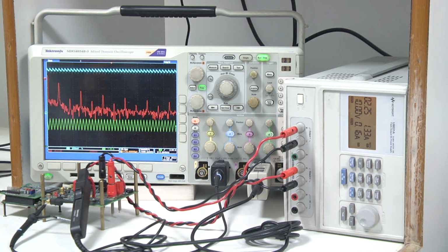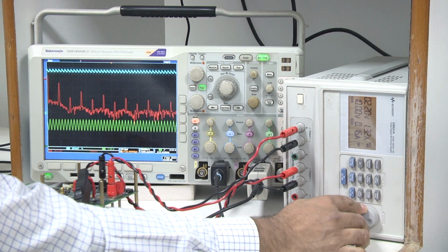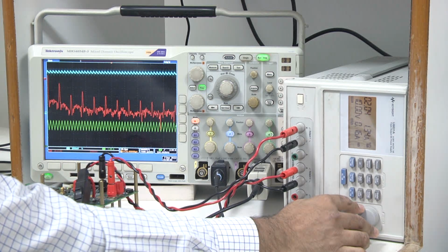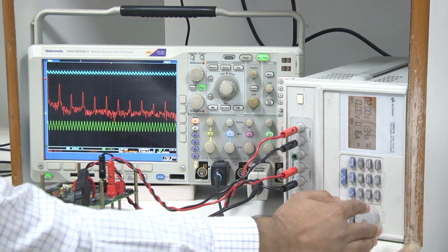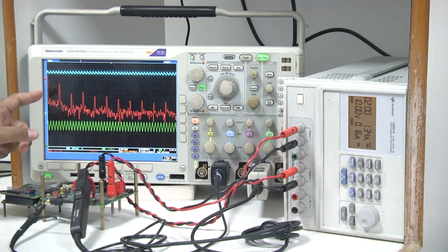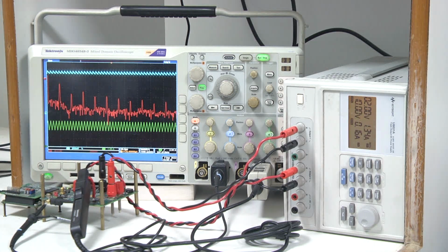So as a result, the frequency is increasing. If we further decrease, that means from 2.25 to 2.2 that we have demonstrated in the class, we are now coming to 2. So at 2 volt input, the frequency is now close to almost 250 kilohertz, around 240, and you can see it is perfectly stable, the valley current is maintained, but the ripple is changing, because we have learned in valley current mode control, or basically constant on time control, for a buck converter, if you decrease the input voltage, the ripple current reduces and your switching frequency increases.